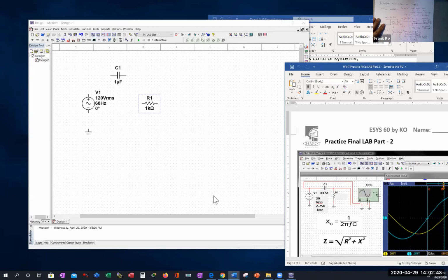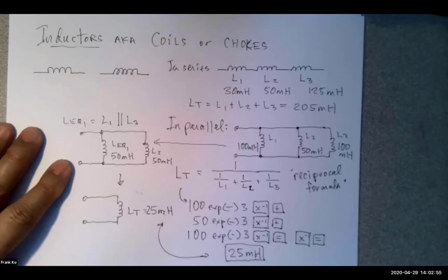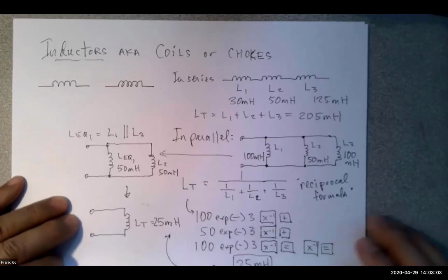What do you remember about deciphering the code for a 472? How do you decipher the code for a 472? We did this before. You do a 4, then you take the 7, and then you put 2 zeros. And that's a good start, right?